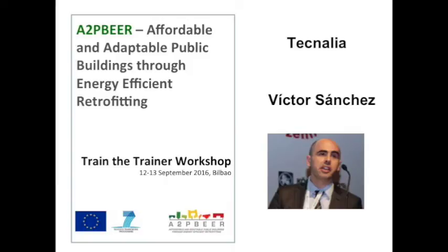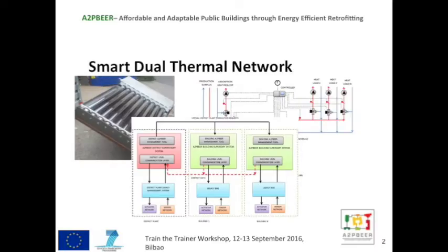In this presentation, we are going to describe an innovative thermal network concept that we call the smart dual thermal network concept that can be used in order to upgrade conventional district heating systems to advanced district heating and cooling systems through the deployment of the absorption collector that Francesca has described to us, the deployment also at the building level of an innovative building substation that we have created, and finally through the installation or deployment of an integrated district energy management system in order to provide model predictive control functionalities.